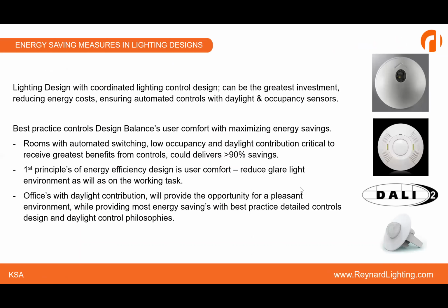Okay, you cannot have office lighting without proper lighting control. We've discussed the motion sensors and occupancy sensors. We also have to discuss the importance of daylight sensors. Daylight sensors are sensors which sense the amount of daylight in any office space.